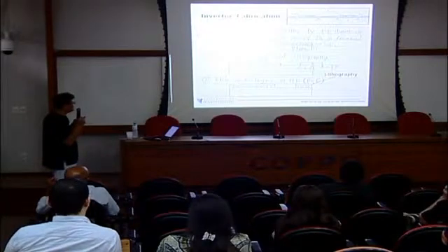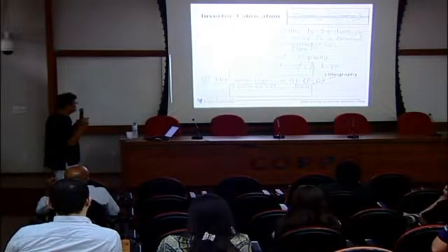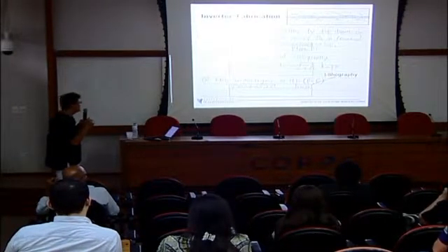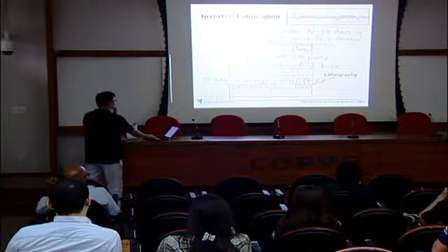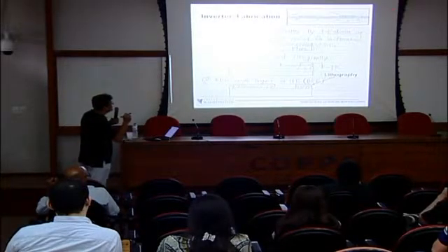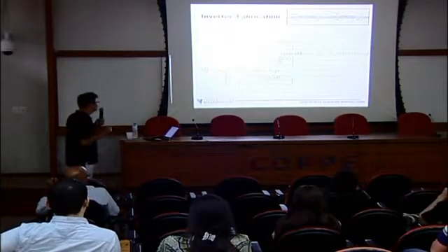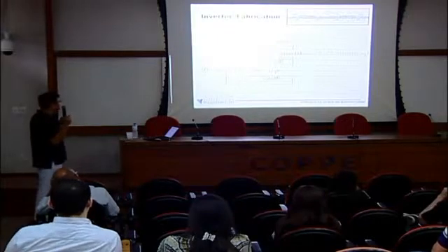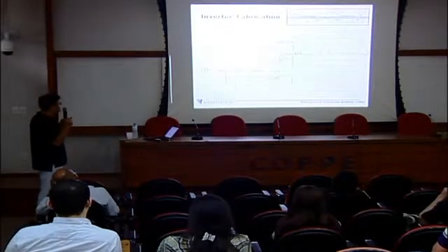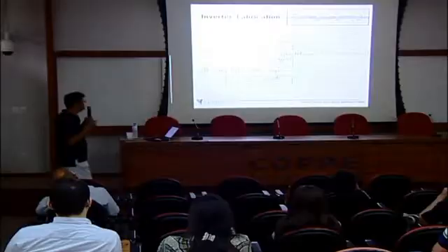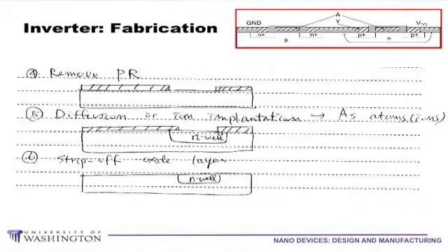layer using this photoresist as a mask. Then we can have a pattern like that. So now we are fabricating this part. Okay? So we need to create an N well through the process. Then the photoresist, that's a polymer layer, can be easily removed in solvent, and then we will diffuse ions into the channel in order to make it an N well.